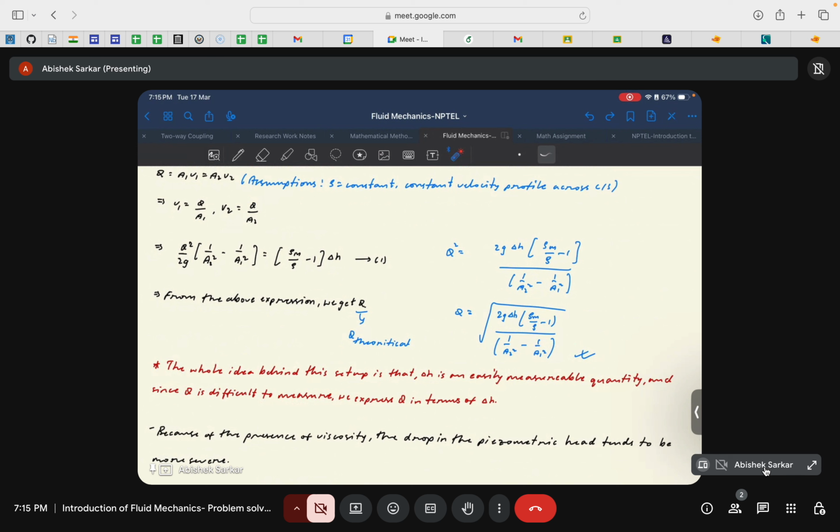You may have to wait a long time to find the volume flow through a particular area. Maybe we store the fluid in a tank and find the time required to fill up the tank of a certain dimension. Then you know that this is the volume flow rate of the fluid through the pipe.